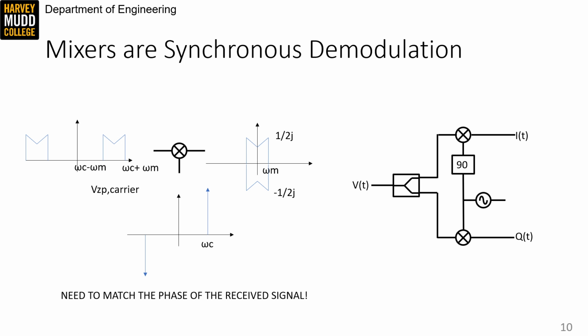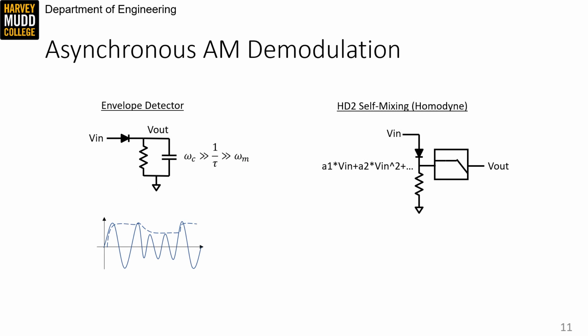Recovering the correct phase to use in a synchronous demodulation is a really involved problem that involves a specialized feedback loop called a phase-locked loop. Phase-locked loops used to align phase like this are often called clock and data recovery circuits, or CDRs. Synchronous demodulation provides very good performance, but it's also possible to demodulate some signals asynchronously, which can reduce design complexity. Amplitude modulated signals are particularly amenable to asynchronous demodulation, which is one of the reasons they were so popular in early radios.